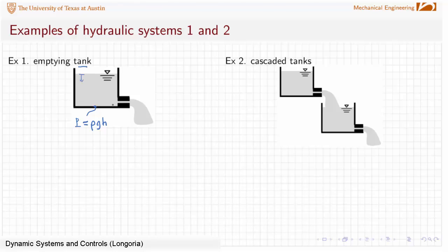So now we've got this symbol here that I'm going to use to represent sort of flow through an orifice. It's going to mean that it's a short section, or maybe even just a hole in the tank. So this is offering some resistance. So we really have just sort of a hydraulic capacitive element, and really some resistance to the flow. And if you think about it, the pressure out here is atmospheric. Pressure out here is also atmospheric. So when we talk about the pressure here being rho g h, we're talking about a gauge pressure, right?